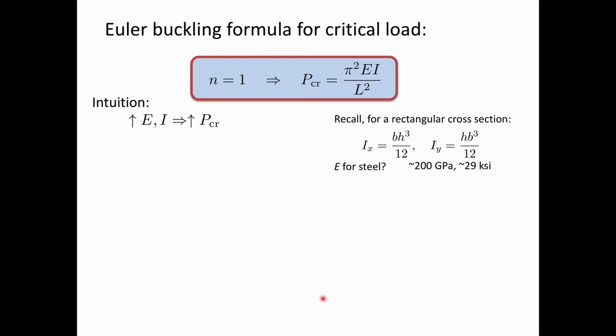Going to different alloys might get us different, say, yield strength or fracture mechanics properties. And so if those other failure modes are dominant, then that could be helpful. But if buckling is the dominant failure mode, then going to a more expensive alloy is not really going to help us very much. It'll add cost, but not really add value.